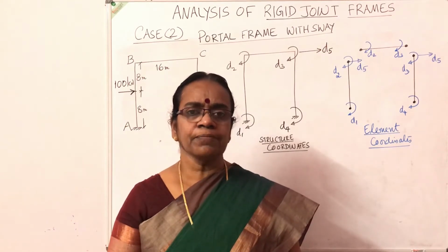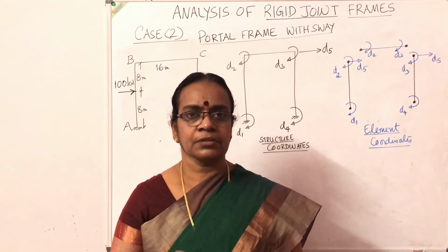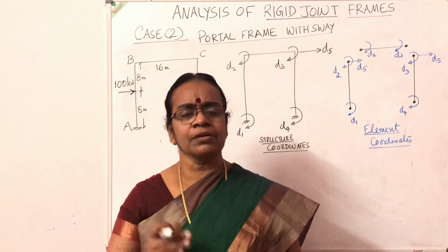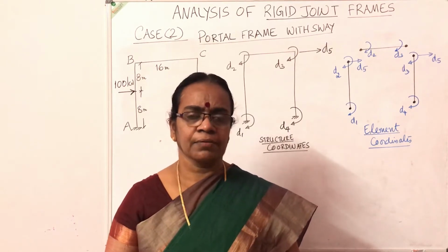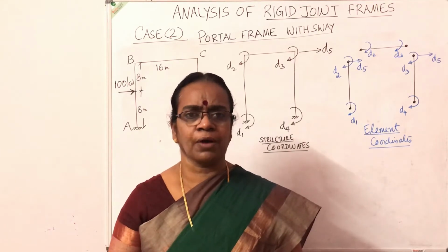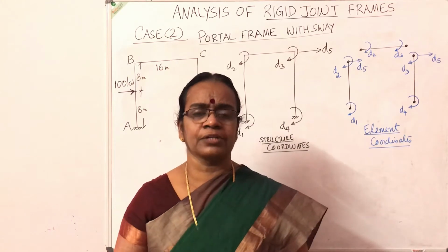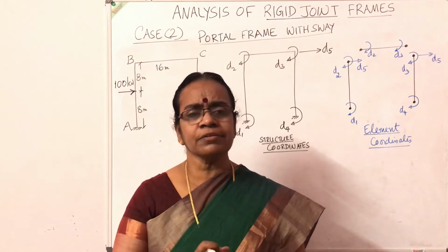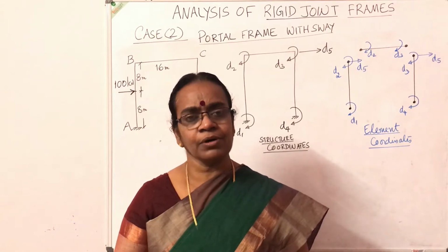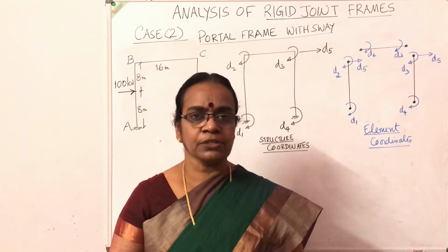I mentioned earlier, if the frame is having any sort of irregularity, or it is not symmetric, with moment of inertia of columns varying or unsymmetrical, varying length of columns, or if there is load from the side or lateral load, in all these conditions the frame will be subjected to sway displacement, or lateral displacement of columns will occur, in addition to the rotation of joints.